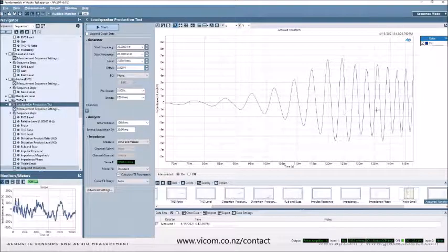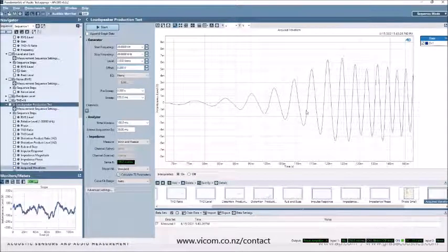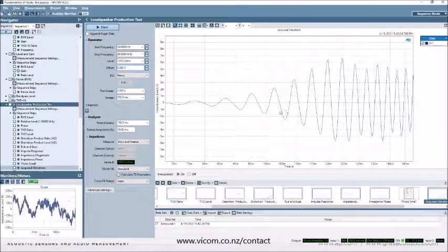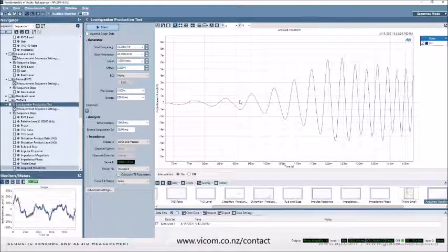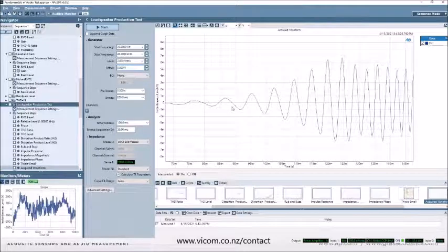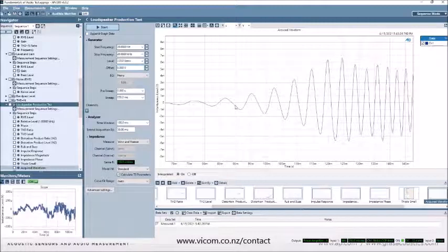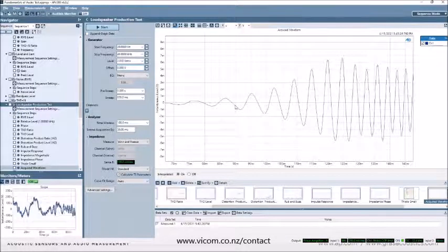You can see the distance between the sine waves is closing. The frequency is increasing. And what's interesting about a log chirp is that it is increasing continuously. Every sample representing this waveform is at a different frequency than the previous one.